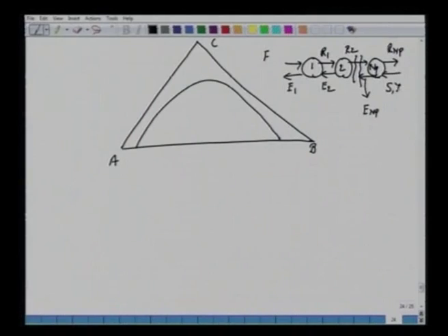Of course this S is YS, it's a pure solvent, so this YS is 0. And here we say that feed composition XF was 50%, so this is 0.5. First thing we should do, we should mark this point. So this is 0.5, which will correspond to 50%. So on this scale we say 10, 20, 30, 40, 50. So this should be 50 here. Similarly, this will increase to make this 100%. So A is 100%. You should be careful with the scale. It represents the amount of A as you go along in this direction. So 0.5 we mark. So this stream composition we have marked.